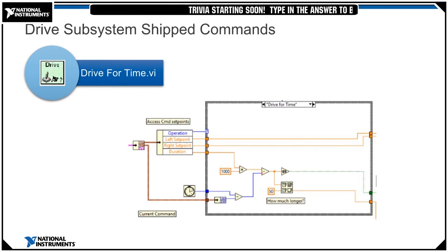If your motors have that safety timeout enabled, it's necessary to update the motors at least once every 100 milliseconds, like our commenter pointed out. So this code is waiting for the smaller amount of either the remaining time or 50 milliseconds. So it's going to wait 50 milliseconds, tick over, see if it needs to wait 50 milliseconds or less, and then continue ticking over like that.